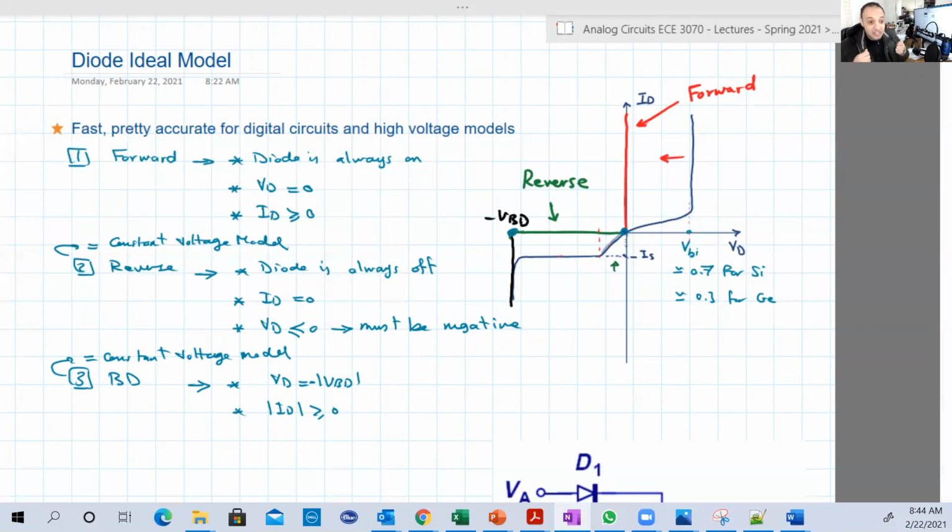So basically, once you see a current, either positive or negative, in either region, forward or reverse, we can consider the diode is on, but on in reverse, in breakdown this time. And that's why we keep saying breakdown, not on, just to have some differentiation between the characteristic of that region in reverse and the regular on region in forward. So our regular on is the one in forward. Basically, for most applications, we want to avoid the breakdown. But you have the model for how to deal with the diode in that way.